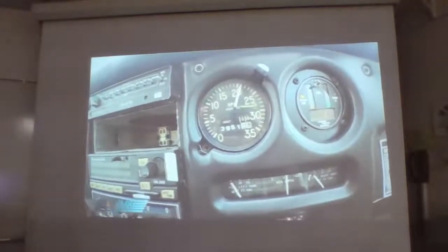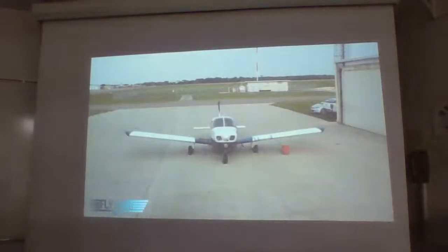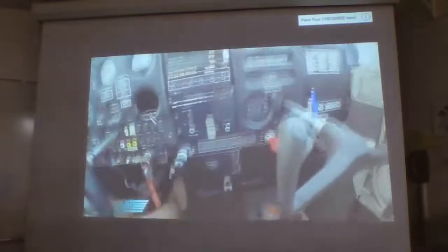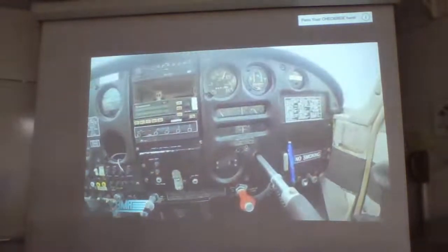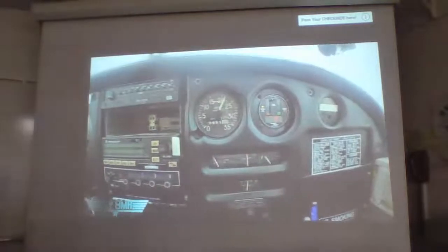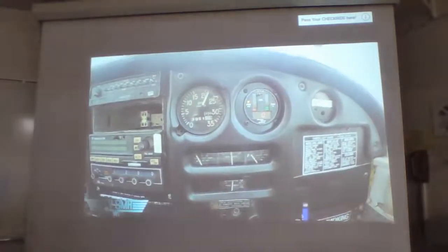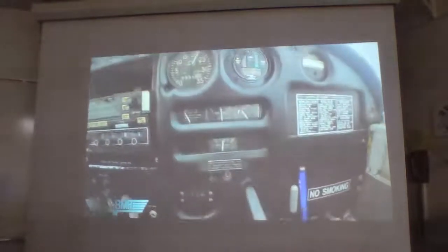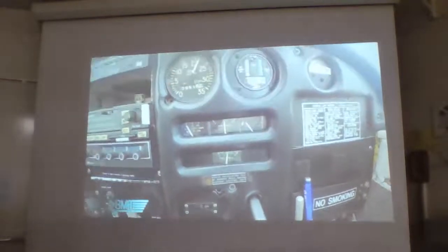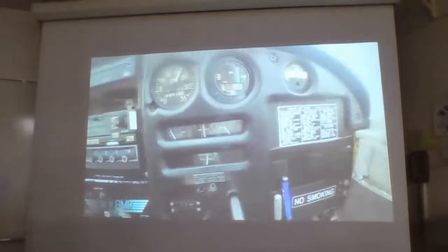And pretty stable there at 2,100. Maybe picking up a little bit of power here as our cylinders get a little warm again. Remember, we had pre-warmed up the cylinders, but things do cool down while it's sitting here. So we can see that maybe as the engine gets a little warmer, it's starting to make more power, actually. We've got good fuel pressure there. Alternator is working beautifully. Almost out of gas.